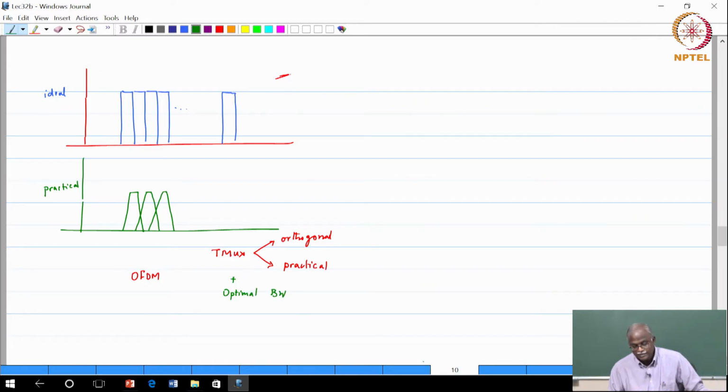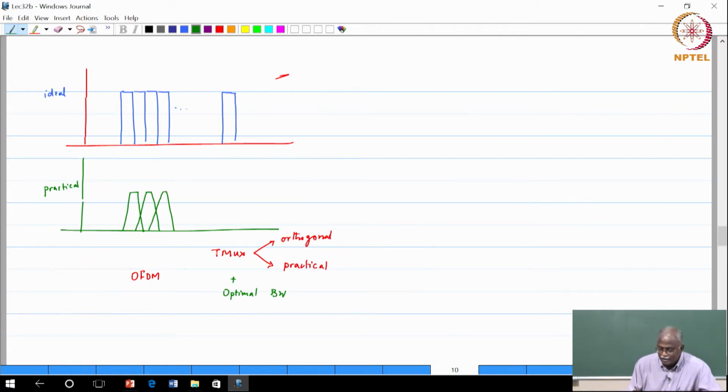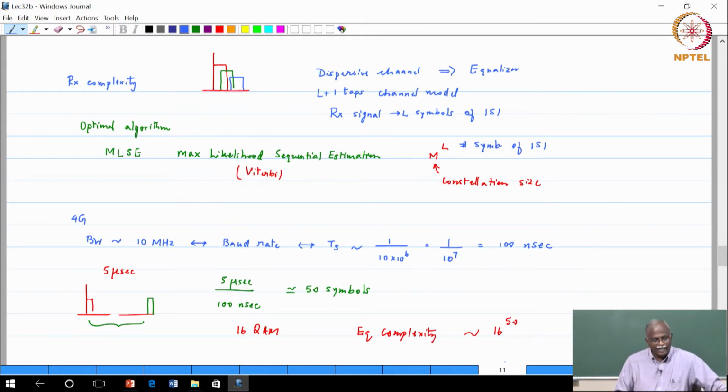Okay. Now, what you are saying is, hey, I have to maintain orthogonality, which means there is going to be overlap, and in the process do not give me guard bands, I do not want to waste bandwidth in guard bands, and if I can achieve all of this, then we are talking about OFDM. Now, you see why OFDM is of so much interest. For the following reason, I can achieve capacity, I can achieve it with practical filters, and I can achieve it without asking for too much excess bandwidth. So, again OFDM becomes a very interesting issue for us. However, one catch is there.